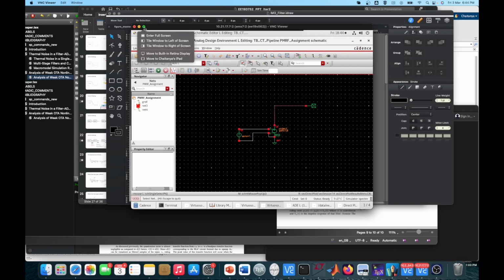No, the peak response won't be at 50 kilohertz. The bandwidth in that question was 25 kilohertz, right? So why would you have peak response at 50 kilohertz? Till 50 kilohertz, it will be falling, and as it is sixth order, it will fall by around minus 120 dB per decade. You will find the peak response near omega naught itself, and that was 25 kilohertz. The 50 kilohertz is just to show that after omega naught the response of the filter is falling.